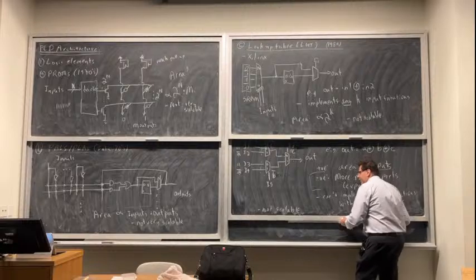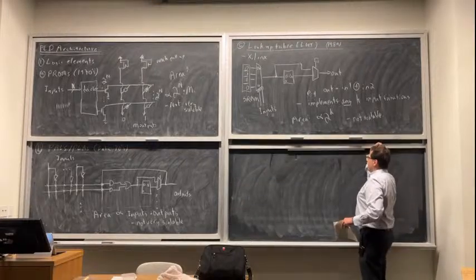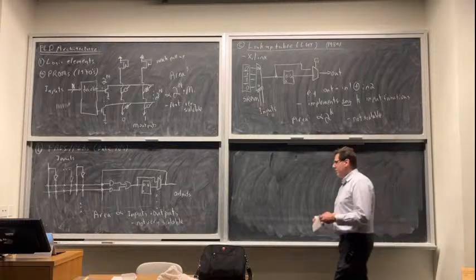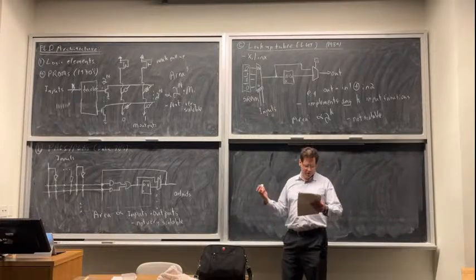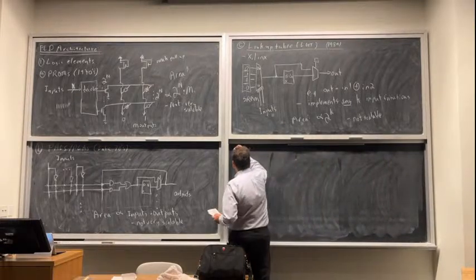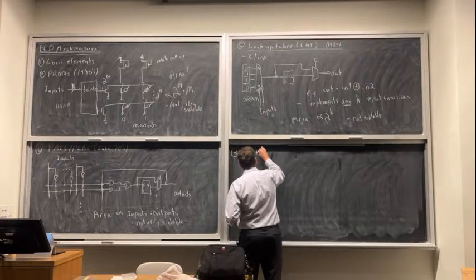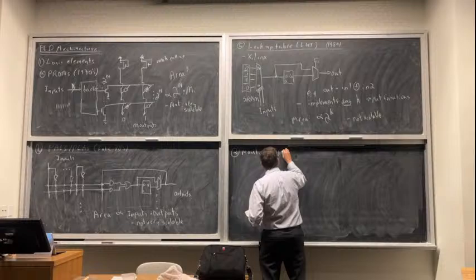So what does this mean? We have nothing where we can just say, let's make huge logic elements. So we're going to make moderate-sized logic elements, and we're going to have to combine them with programmable routing. So we need routing networks. That's the second big part of an FPGA.